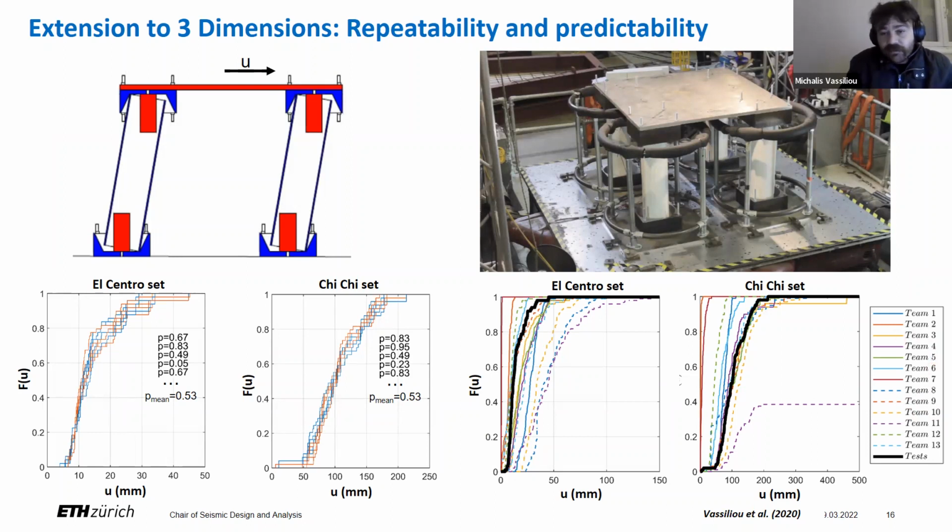Now, some interesting observations. Both finite element and discrete element models can perform well or poorly, depending on the parameters used. There is no basis to recommend finite element against discrete element or vice versa to model 3D rocking structures. The models that performed the best used zero or extremely low Rayleigh damping. However, they did include an energy dissipation mechanism. They explicitly modeled friction. This shows that damping should be modeled with methods that make sense physically. Rayleigh damping doesn't.